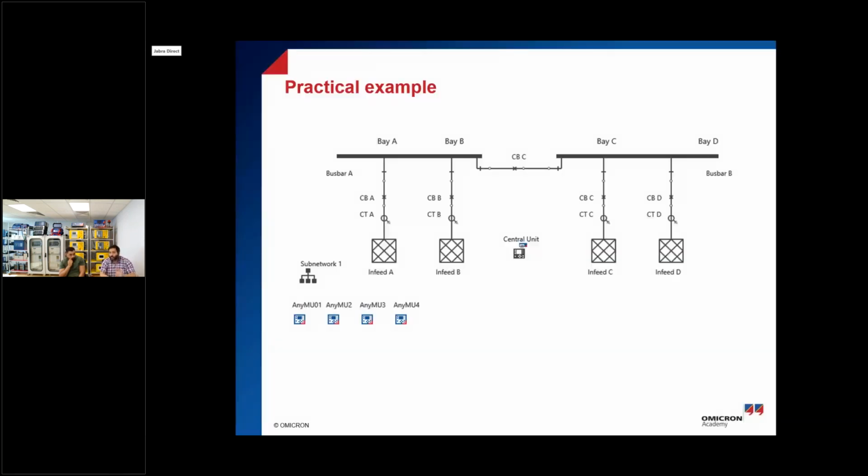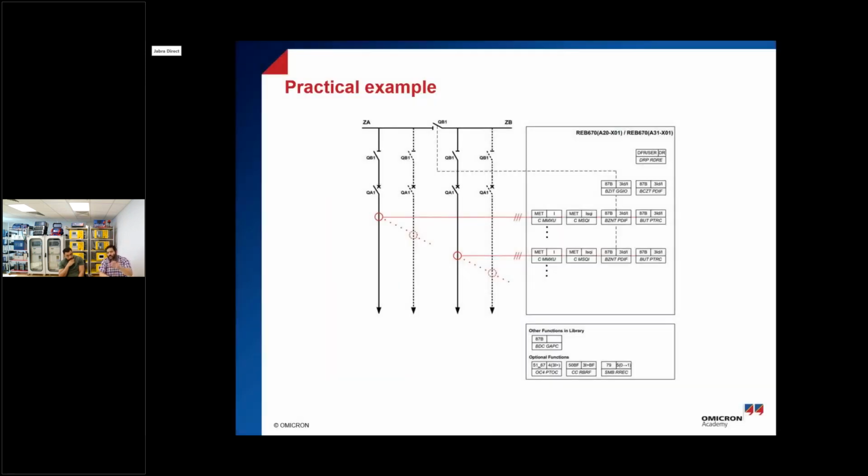Another scheme, which I will actually use, this is what we will use today. We will have single bus bar with bus section, and 4 outgoing feeders in this scheme. This is what we will test today. And actually here I will have ABB RET 670 as a centralized system. And this is from the relay manual. This is the example which I really applied here.